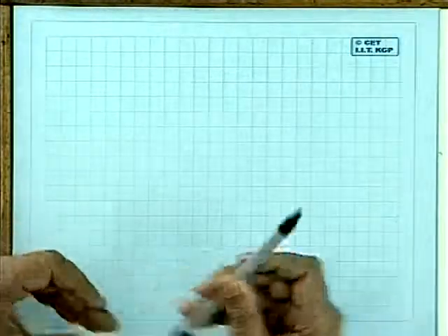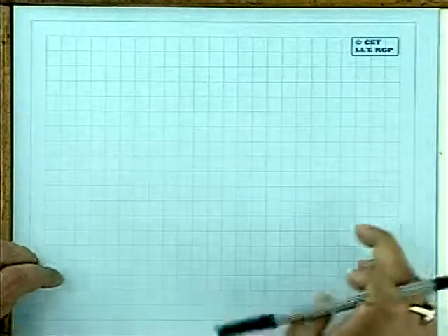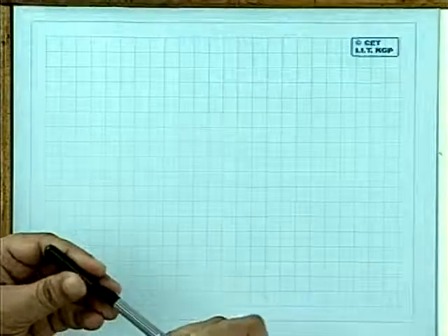We have discussed the gallium arsenide MESFET. I just told in the last lecture that a gallium arsenide MOSFET was technologically difficult. So the gallium arsenide MESFET, using a Schottky barrier gate instead of a MOS gate, was realistic and was developed to a great extent, and I have discussed something about it in the last class.